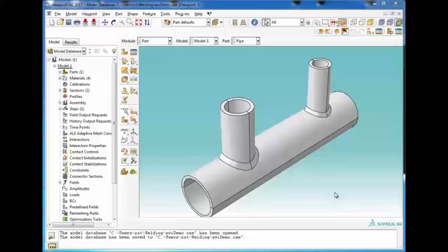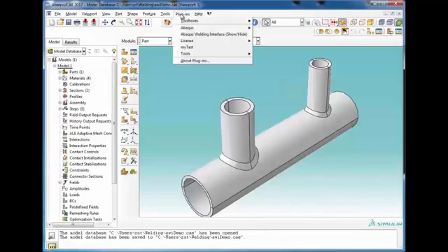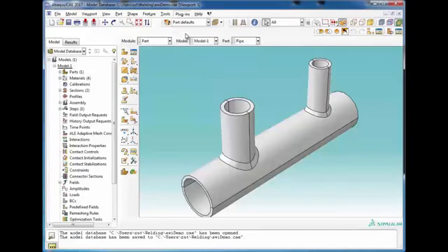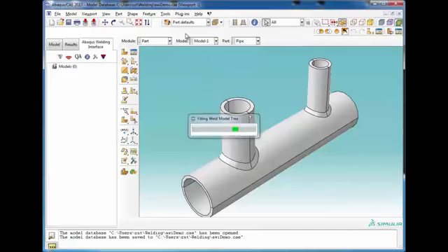Welcome to a demo of the Abaqus Welding Interface. The AWI, as we call it, is a plugin that was developed for Abaqus CAE that specializes in setting up weld models. When we bring it up, we see there's a tree here. We have options like bead color coding, highlighting, some QA tests. These are useful if you're new to the plugin. You can run some of the example problems and get the feel for how things are set up. There's a user's manual, an option for installing workshops, and then the post-processing.